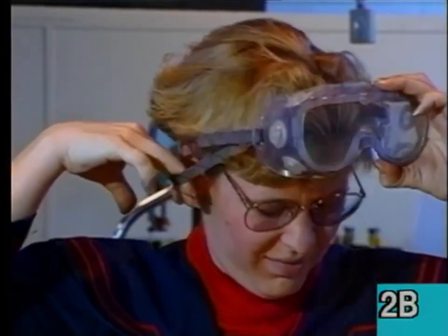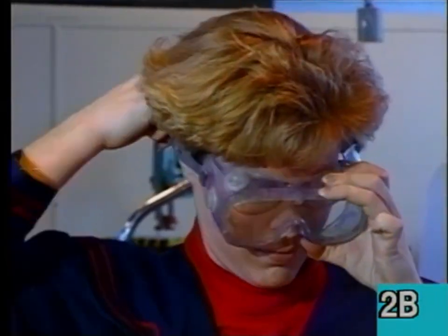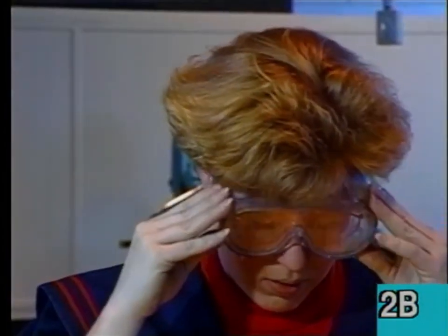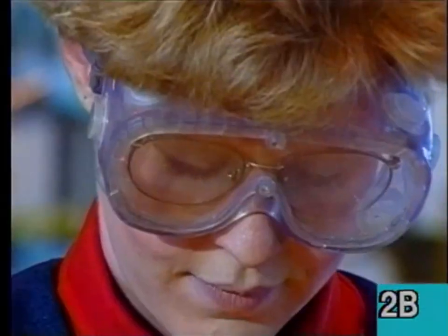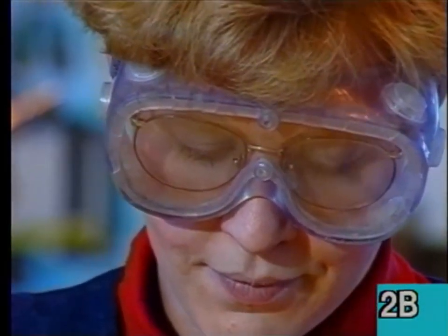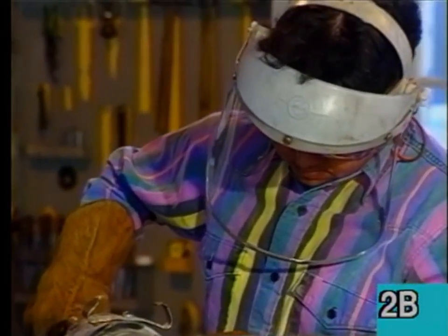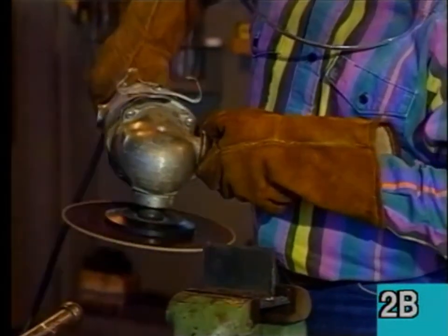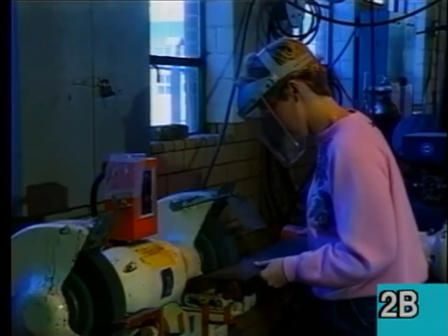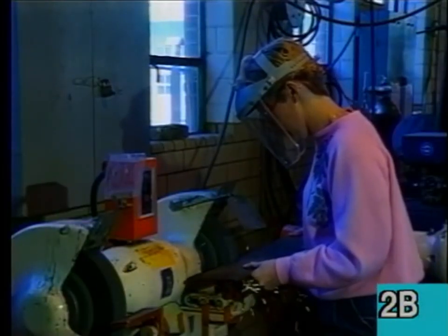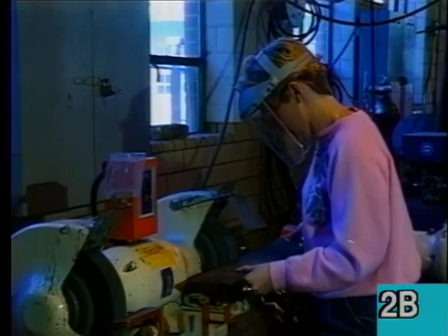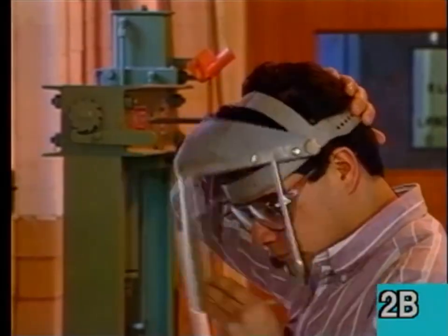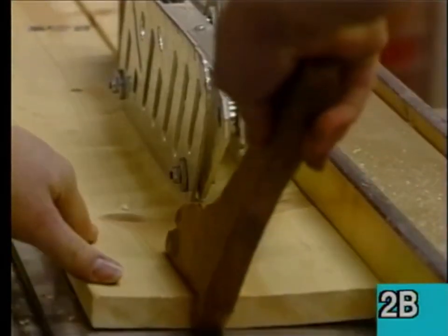People who wear glasses to correct vision have 2 options available to protect their eyesight. The first is to wear safety goggles over their glasses. The second is to have prescription safety spectacles made. Clear face shields are sometimes recommended in situations where there is a danger of fragments being thrown at the face of the person who is working. Remember, clear face shields alone provide excellent face protection, but inadequate eye protection. Safety glasses or safety goggles must be worn under face shields to provide full protection from penetrating materials.